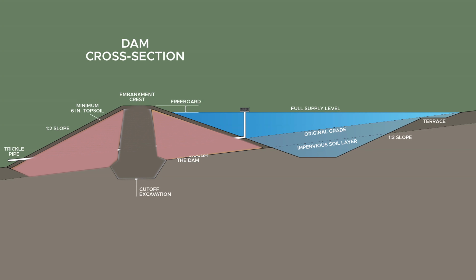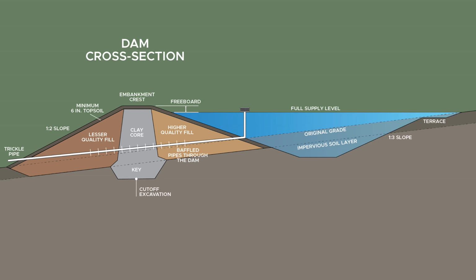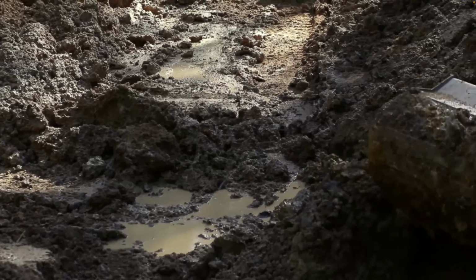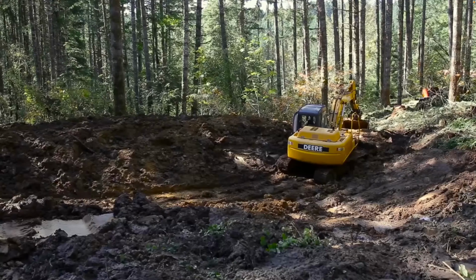And as we go up every couple inches, we want to make sure that we get adequate compression on the top of this dam wall to make sure that it gets really compacted and stabilized. Usually it's really useful to use a sheep's foot roller to do that compaction, and there's calculations that can be made by volume and by the type of clay that we're working with to determine how much weight and how many passes of a roller we need to utilize in order to get that good stability.